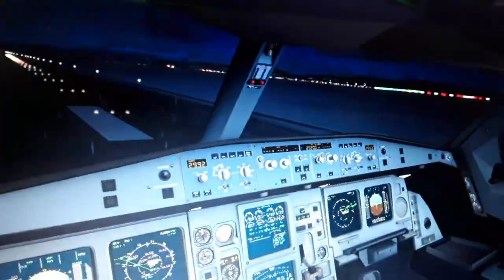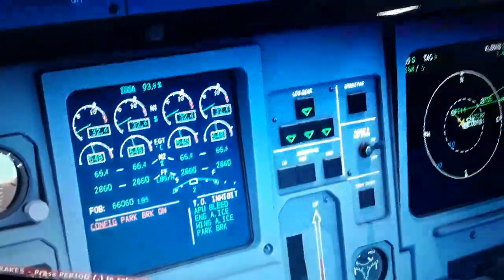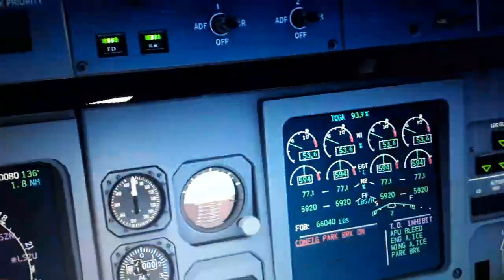We have another 32 minutes for this flight, so we come here, we're going to take off now. This is another look of the runway, the aircraft, ready to take off, 31 minutes. So we move the thrust levers to the takeoff go-around position. You will see the engine thrust increasing and the mode here, the takeoff go-around. We are ready to take off.